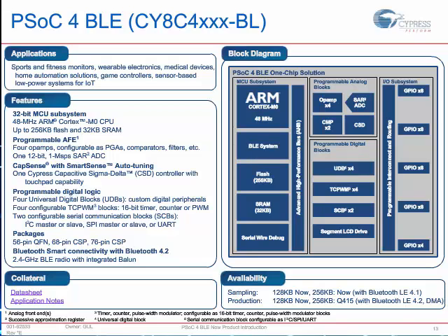And finally, to wrap things up, the chip is available with up to 36 GPIO, all of them CapSense capable, or all of them that can be used as analog inputs or digital outputs. All of the IOs are configurable. Keep in mind, though, that the module that's available today only offers a 16 IO version. The chip offers a 36 IO version.